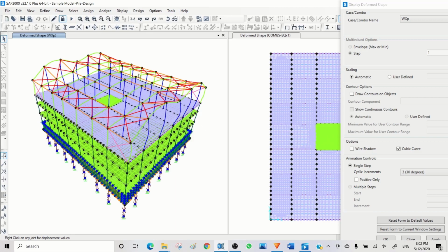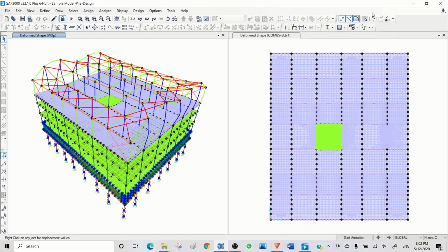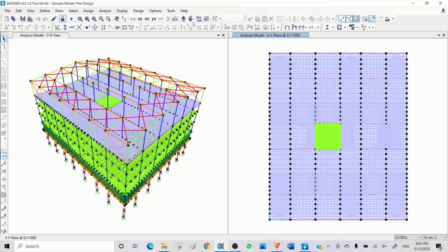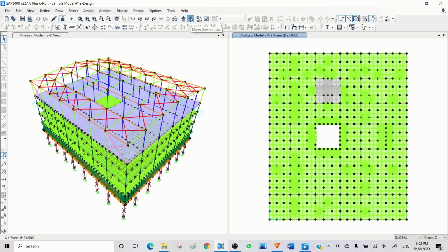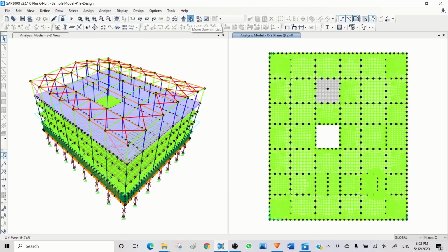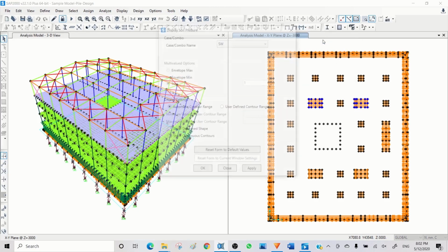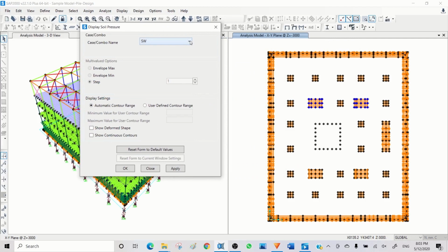So I'm checking soil pressure for you guys for sizing the foundation. I'm coming here and here, on the form shape, and then I moved on to the foundation. For sizing the foundation, if you remember, we have two foundations on area spring, which is pad footing. The rest are pile foundation and pile caps. So when I want to check those, I'm coming here, checking the soil pressure. I need to use working stress for soil pressure.